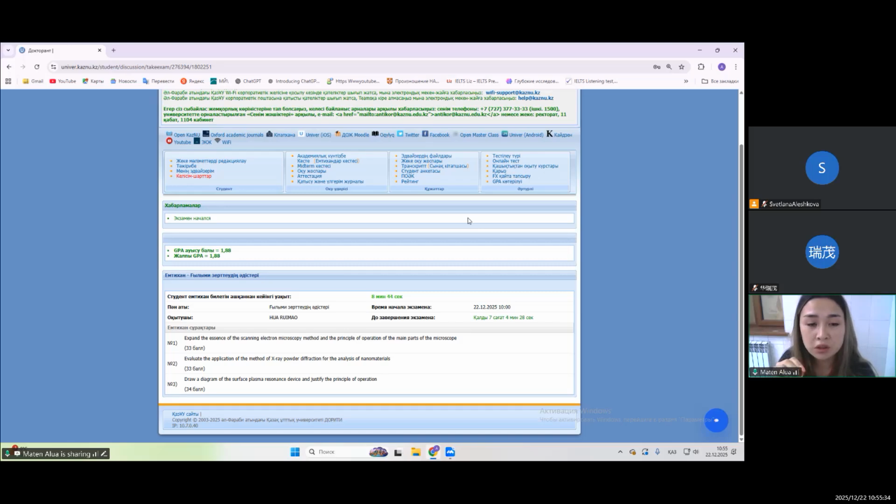And the advantages and limitations: XRD is non-destructive and provides reliable bulk structural information. However, it has limited sensitivity to amorphous materials and cannot directly reveal local defects and surface chemistry.